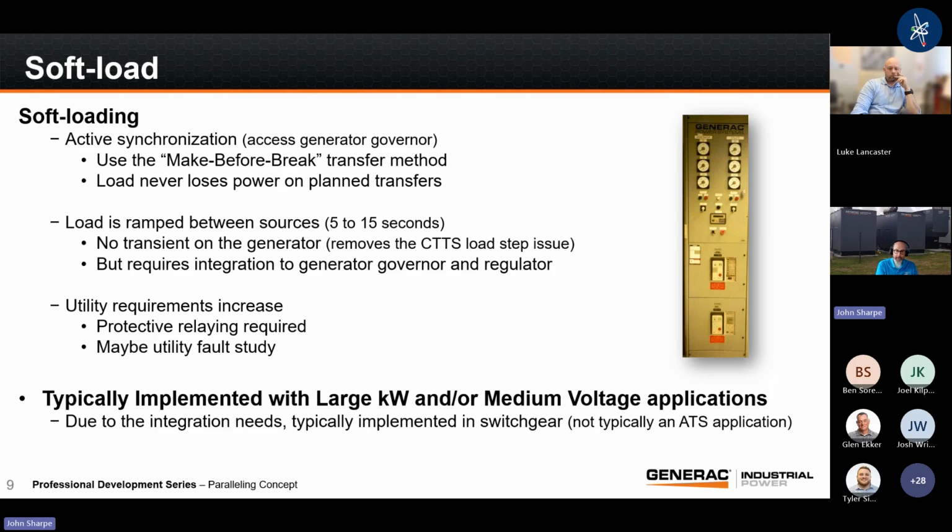When you make that transition, we're not shutting off any loads, right? Like I said, it is a smooth transition or closed transition between the two. So if the building is running at 300 kW or 500 kW of load, when we hop back to the utility, that's 300 to 500 kW of load that's going to hit, boom, in 100 milliseconds onto the utility. Some utilities are not prepared for that.